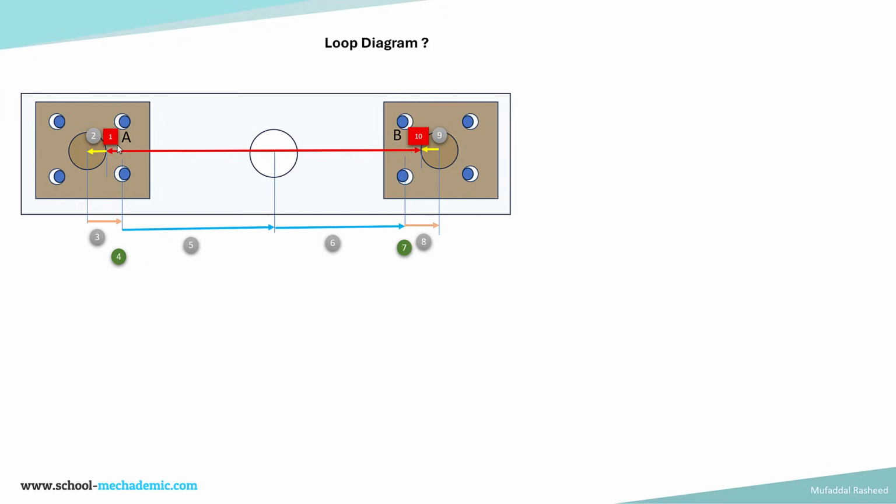So the worst case is it moves towards the left, and there is an assembly shift, which is denoted over here by these fasteners which are contacting on the right. So that is accommodated in this specification, which is specification number 4. That is the assembly shift of this post with respect to the bottom plate. Then the location of the pattern of 4 holes with respect to the center hole is specification number 5.